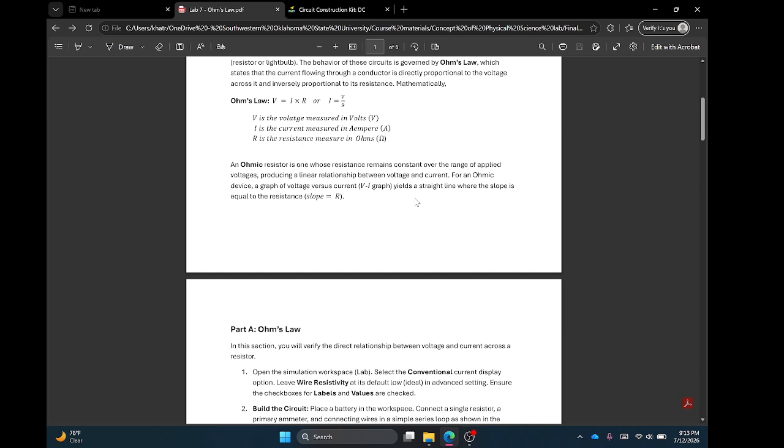So if we have an experimental setup such that we can change the voltage for a certain resistance, it will automatically change the current, meaning, what I'm trying to say is, if we record electric current as a dependent variable based on the voltage, we can create a linear graph between voltage and electric current, and calculate the resistance using these relations.